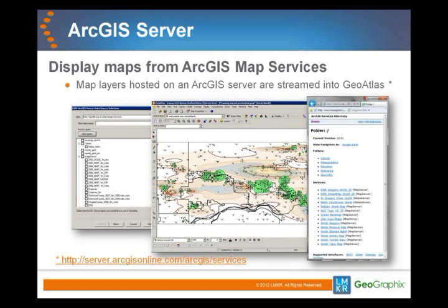So that's really the difference. The ArcGIS Map Service simply allows you a little bit more ability to figure out what's on that map. It's not just a static image like a satellite image. You can actually click on the map in some cases, not every case, it depends on how you set it up, and get some information. So, for instance, if it was a lease, you might be able to click on that lease and have a little dialog come up and say who's the lessor, who's the lessee, and when the lease expires, et cetera.